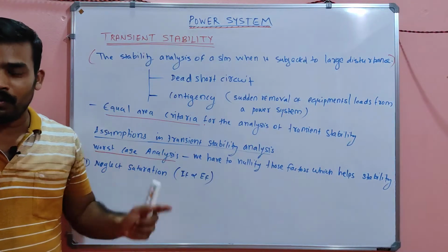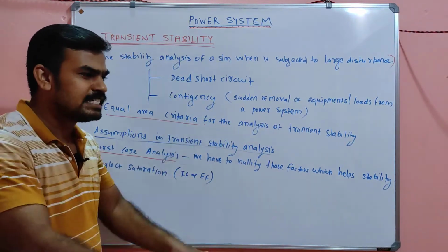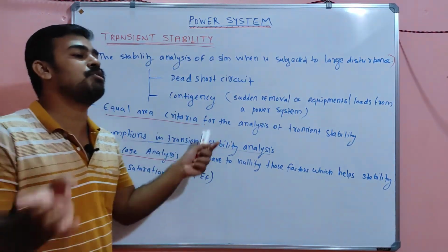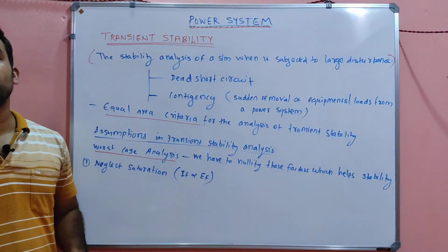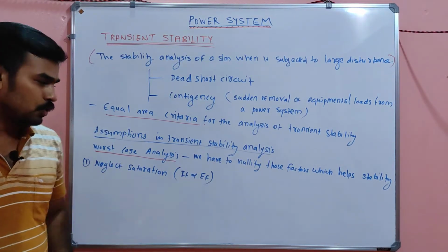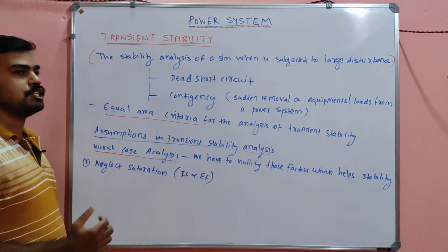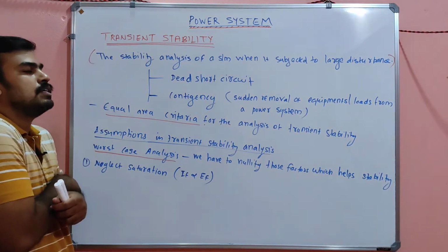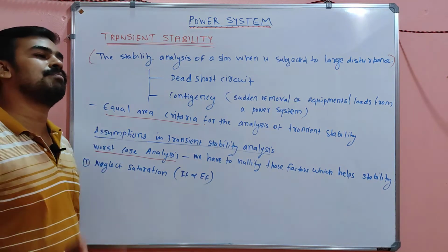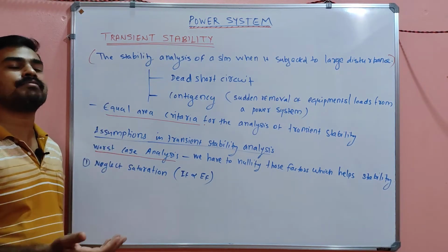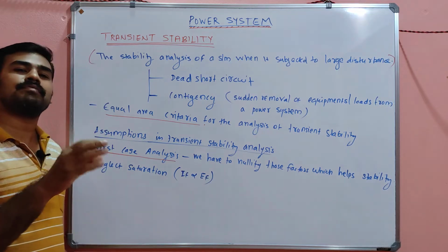Is it good? No. We have to take the worst cases and analyze them to find the stability criteria of the system. If you include the point of saturation, it is a comfort zone for the analyzer, so that even if after some point you increase the field current, the field EMF doesn't change.